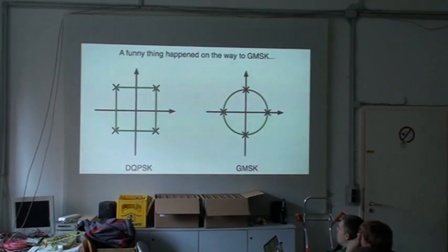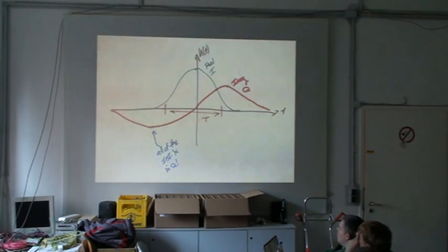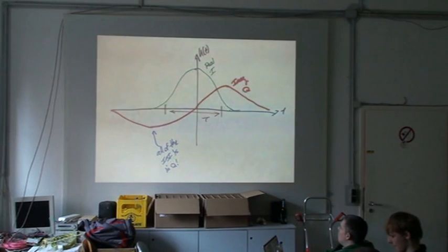The way that happens, you can think of it as BPSK with a complex valued channel filter. Because it's a complex valued channel filter, the signal can deviate from the real axis during transitions. If you draw this channel filter out, it's a Gaussian filter, and then there's another component that's kind of like a Gaussian but 90 degrees out of phase.